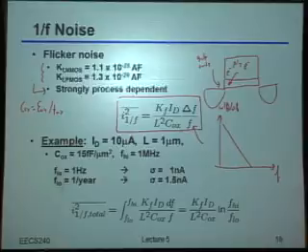Okay, so you said that if you decrease the thickness of the oxide, then maybe you have actually fewer physical traps. That might be possible, although that would probably be captured more by that KF parameter. This is actually really just directly related to how the charge causes a noise in the first place. In other words, even for the same defect densities and everything else, I claim that if you reduce the thickness, things will get better. So the higher capacitance, you have a lower change in VTH for a trapped charge.